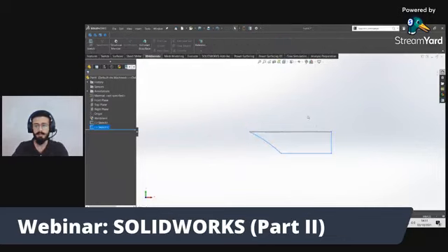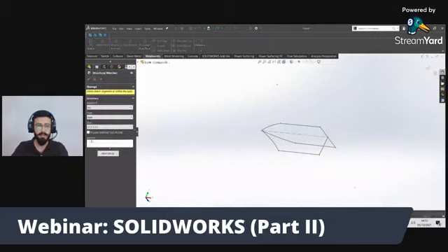And this is our whole structure, we want this type of structure. Just go to weldment, structural member, and then there is an option, groups. I will be showing, let's see, square tube. Square tube was a bit small.